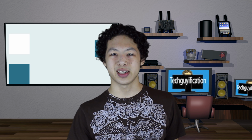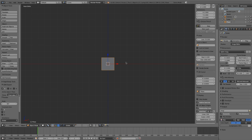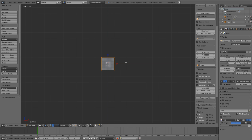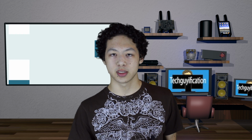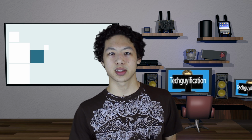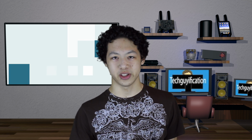So next, make sure that the plane is selected and hit tab on the keyboard to enter edit mode. Within edit mode, press A once or twice to make sure all the vertices and faces are selected, and press X and select only faces. So now all we're left with is vertices and edges.